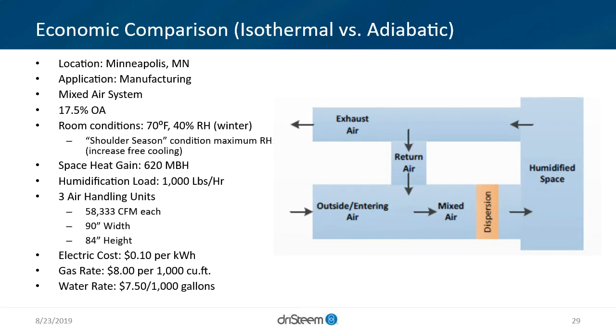So really the meat and potatoes of the operating comparison, looking at these systems, is looking at first, what's your electric cost annually? The 2 notes for the electric resistive and gas to steam are these systems would be potable in this example, and why there might be a little bit of an apples to oranges situation, since high pressure atomization does require water treatment in the sense of RO all the time. Not to say that you can't use RO with these other technologies, but what we've typically seen is they tend not to use it if they can.